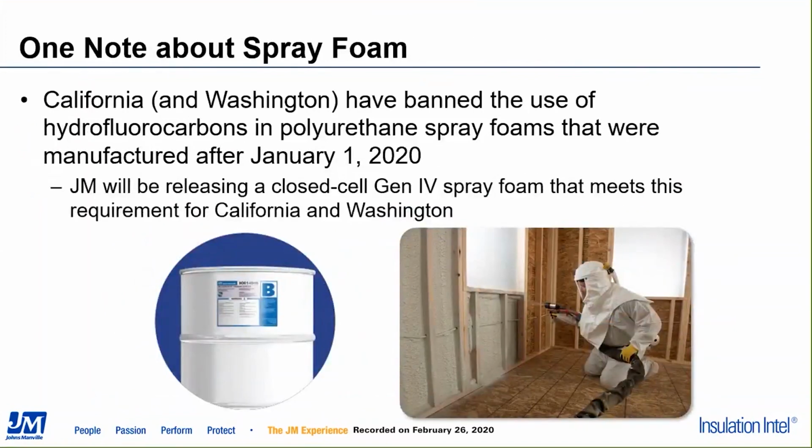One quick note, though, about spray foam that maybe has come to your attention. California and actually Washington, just starting this year, have banned the use of hydrofluorocarbons, or HFCs, in spray polyurethane foams. And where this really comes into play is on closed cell foams. Johns Manville will be releasing what we're calling a Gen 4 closed cell spray foam that actually meets this requirement, and that'll be happening later this year in 2020.